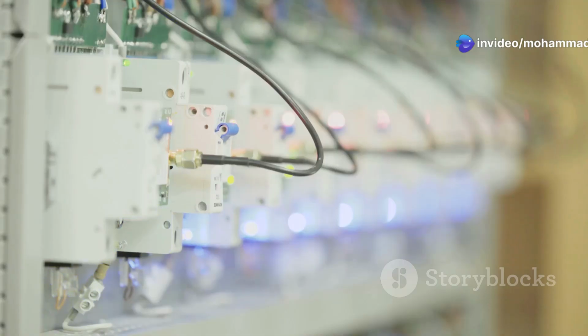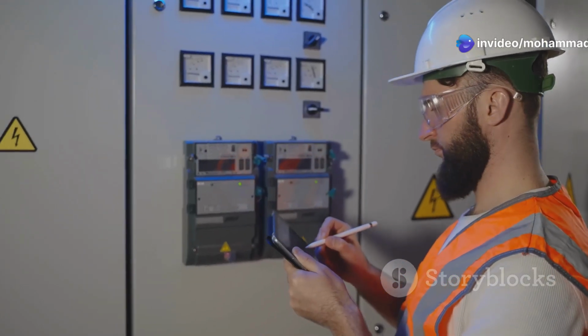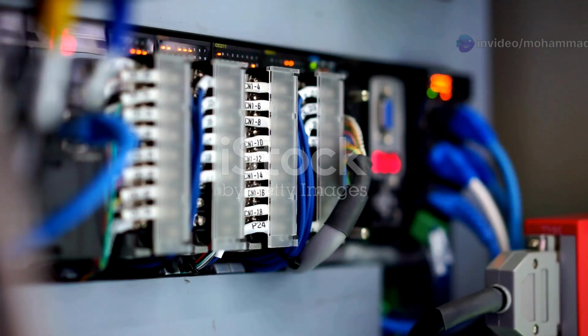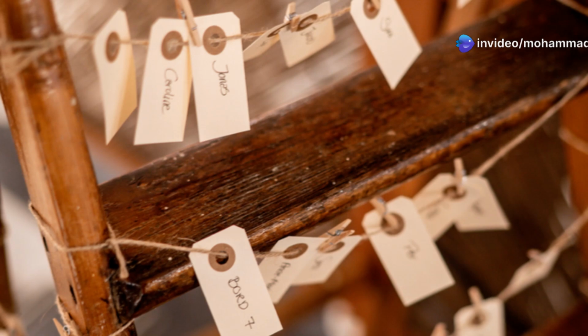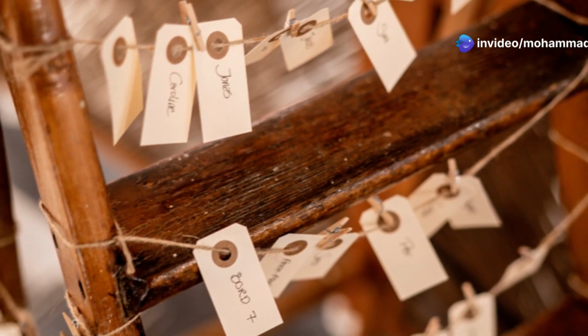For instance, a simple circuit diagram might depict a power source, a switch, and a motor connected in series. The symbols for each component, a circle with a plus and minus sign for the power source, an open and closed line segment for the switch, and a circle with the letter M for the motor, are connected by lines representing wires. More complex schematics like those for PLCs use ladder logic diagrams. These diagrams resemble a ladder, with two vertical rails representing the power supply and horizontal rungs representing individual circuits. Each rung contains symbols for inputs, outputs, and logic functions, illustrating the program's flow.